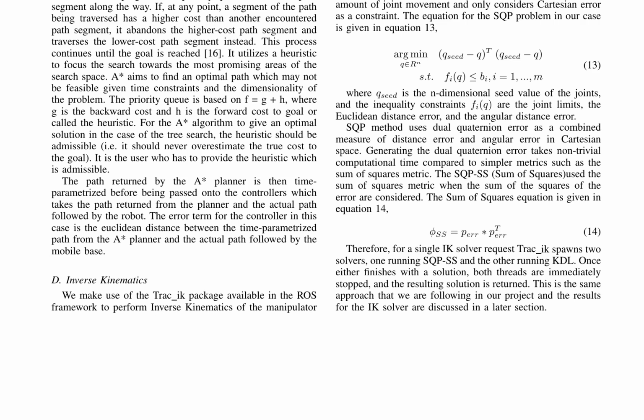The Fetch robot serves as the implementation platform, with its kinematics specified by the robot's Unified Robot Description Format, URDF, model. The URDF model describes the attributes of the joints, links, and frames of the robot, including inertia, visual features, and coordinate frames. The Denavit-Hartenberg, DH, parameters and system dynamics derived earlier are used to populate the URDF model. The coordinate frames for all links in the Fetch and Freight are defined with a positive z-axis up, positive x-axis forward, and positive y-axis to the robot left when in the home pose.